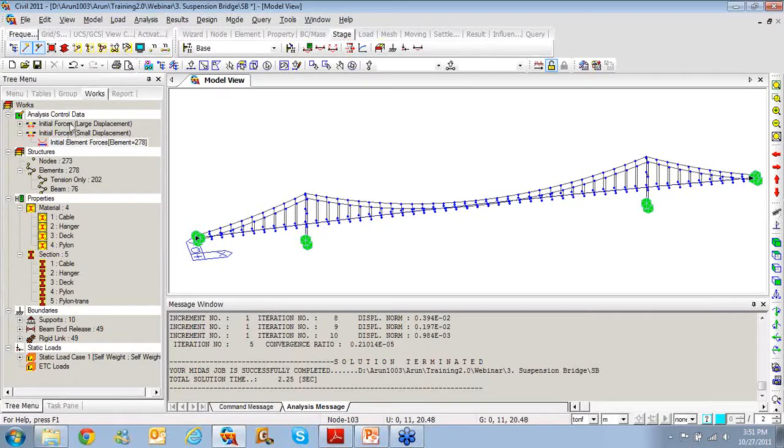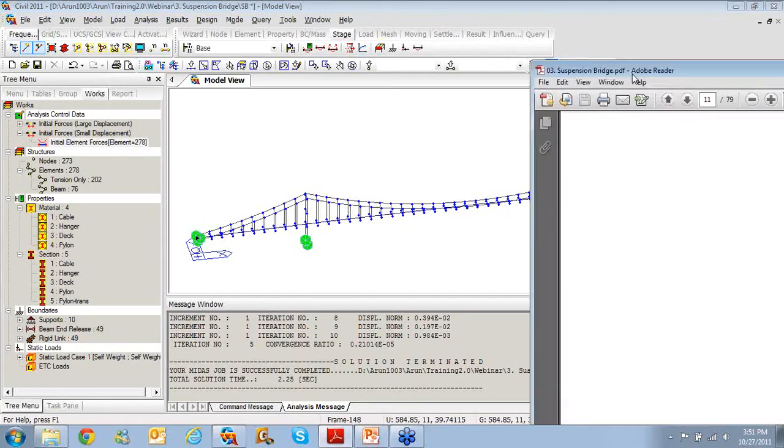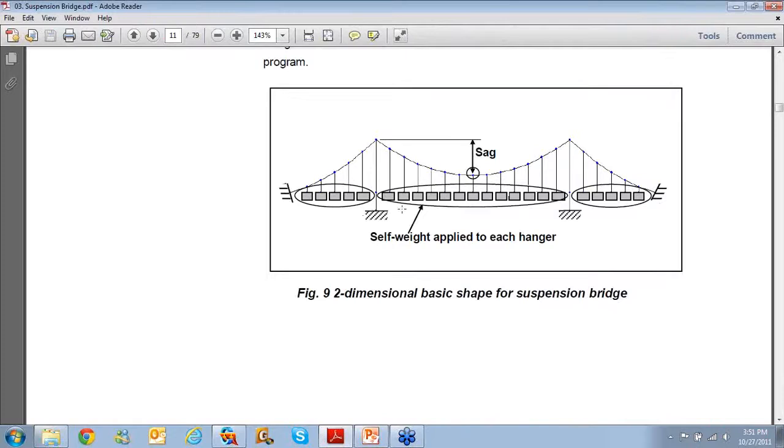So now the final touches. Let me bring back that image. Now since this kind of setting or the boundary condition was needed to assess the geometry and the initial forces for updating the cable forces, but in real completed state analysis, this complete deck is rigidly connected to the structure. So what we'll do is we'll delete all the pin connections that we just created,